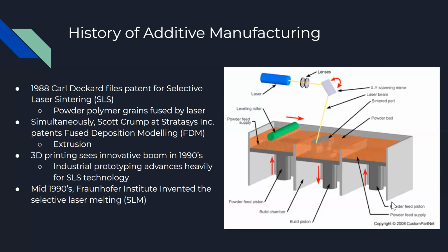The industrial manufacturing industry turned to additive manufacturing for new ways to rapidly produce intricate products. The Fraunhofer Institute built upon the SLS, the selective laser sintering process, using a newer, slightly derivative method called selective laser melting, which only differs from sintering by fully melting the target area of the powder bed to fuse it to other particles. This would prove useful in some heavier duty applications.